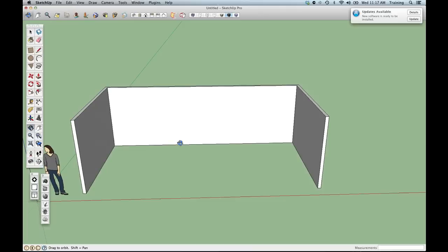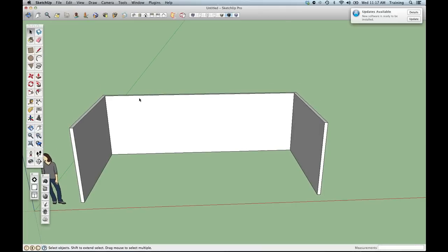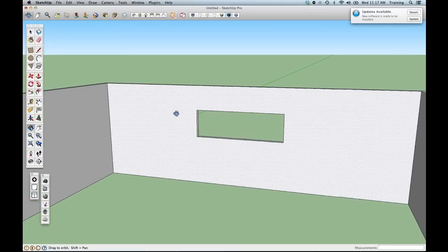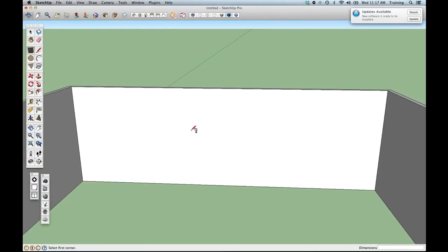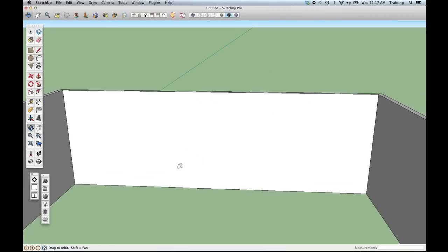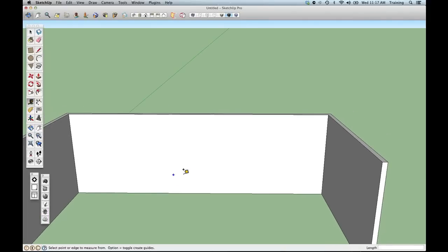So, all right, let's say on this wall I wanted to map out a window in the wall, which I'm eventually going to punch a hole through, and then we're going to actually install a window into it. To do that, I'm going to put a rectangle on the wall like that, and I'll use the push-pull tool to punch the hole in. Now there's a problem here in that when I'm drawing with the rectangle tool, I have no way to actually locate the rectangle exactly where I want it. And since I have real field measurements, I want to be able to use those so that my window is in the right spot. So the question is, how do you do that? And the answer is we can actually use the tape measure tool. So let's say we have some dimensions on this window, and let's say we know that the center line is 11 feet.